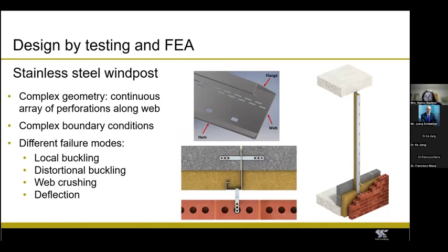You can see a complex geometry. It's a lipped angle section, continuous row of perforations, complicated connections back to the blockwork. So SCI devised a test program and then supplemented the results with numerical analysis and developed a methodology in accordance with the Eurocode, and carried out a reliability analysis.